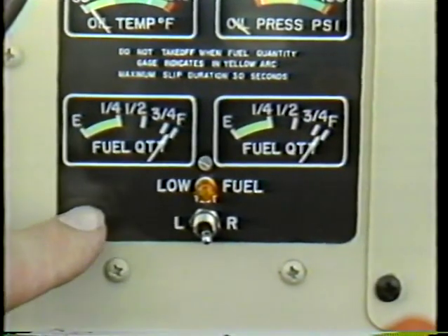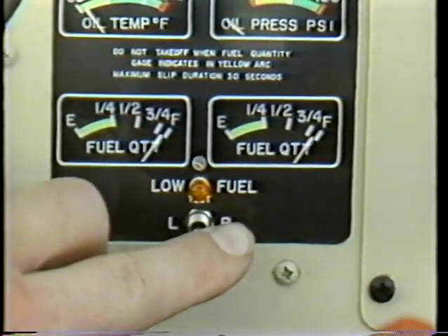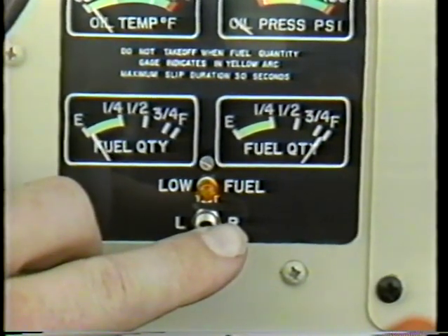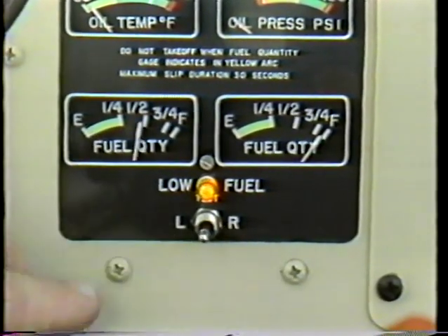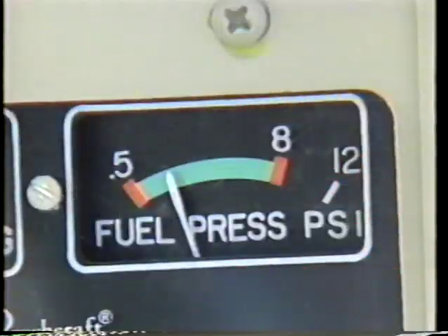The system quantity will be indicated by a fuel quantity indicator system in the cockpit to tell you how much fuel is in each tank. If you find that the fuel quantity indicator is inoperative, you must get it repaired, because this system is required to be operative according to the Federal Aviation Regulations. In some cases we may have a fuel pressure indicating system and also a fuel warning light that tells us if the fuel pressure is low.